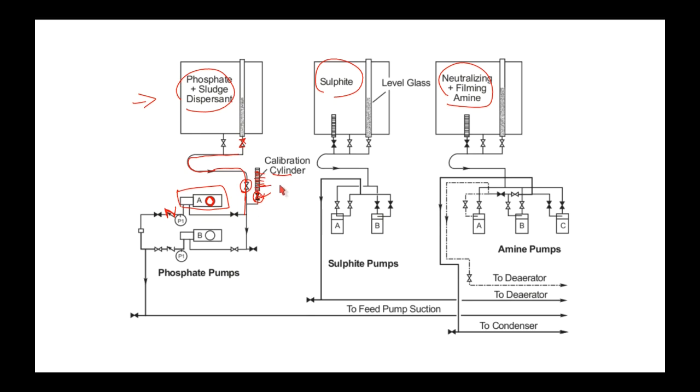So I do a 30-second drawdown, and I record the number, and then I flip the valves back into the normal operating position. And maybe you didn't quite get it right, so you might have to do this 5 times for each chemical to get the drawdowns correct.